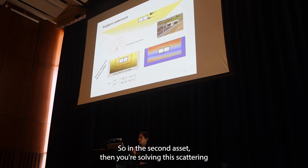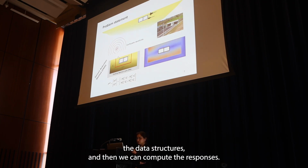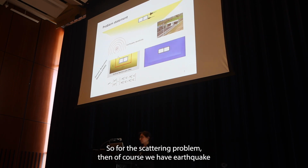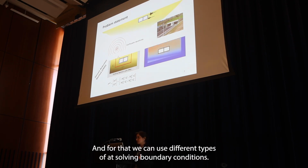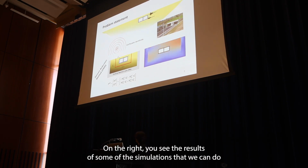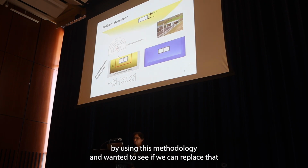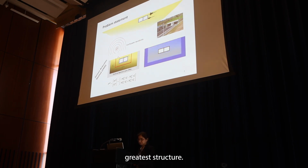In the second step, we are solving a scattering problem with the localized heterogeneity involved, here the buried structure, and then we can compute the responses. For the scattering problem, of course, we have outgoing propagating waves coming from that structure, so we need to absorb them, and for that we can use different types of absorbing boundary conditions. Here I'm showing an example of using perfectly matched layers. On the right you see the results of some of the simulations that we can do using this methodology. And we wanted to see if we can replace that with a surrogate model that can still predict the response of the buried structure.